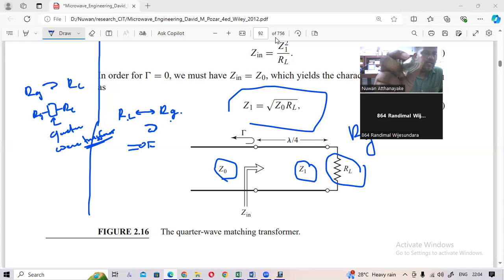Normally we use this for half-inch coaxial cable. That means the diameter of the coaxial cable is half-inch. And there is another, N type, that is also used for half-inch cable. And 7/8 coaxial cables are there. For that one, we use a 7/8 connector. So different types of connectors are there. But in labs, we are mainly using this type, the SMA connector, and the BNC connector.